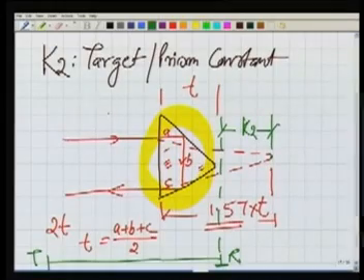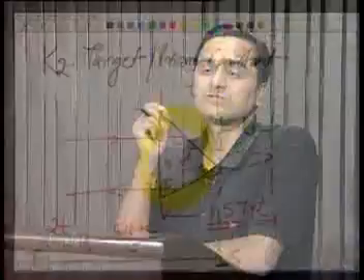So, what we have seen today: we saw the principle of EDMI, how they work, what their types are, whether they are wavelength dependent, or their range, or the different kinds of reflectors. Then we saw their basic principles. They can make use of the time of travel, measuring that time, but they are costly. The EDMI mostly used in our land surveying makes use of phase measurement, or the phase difference.